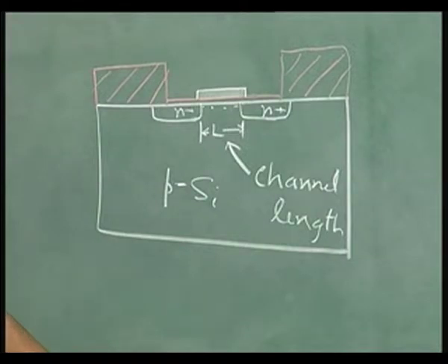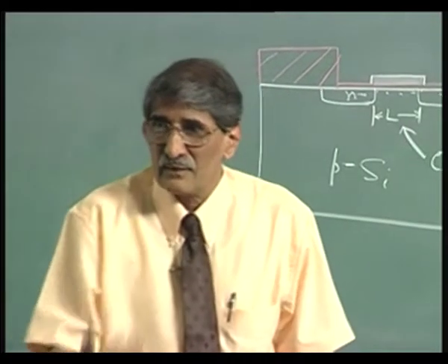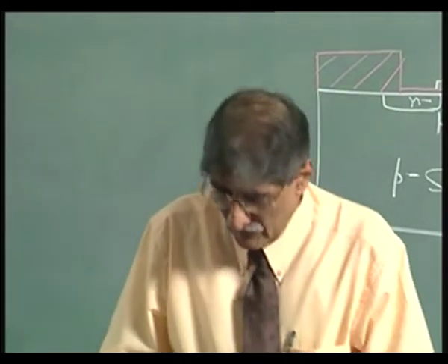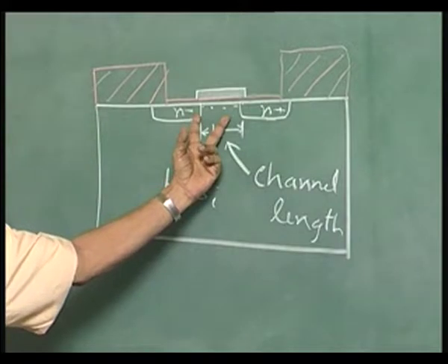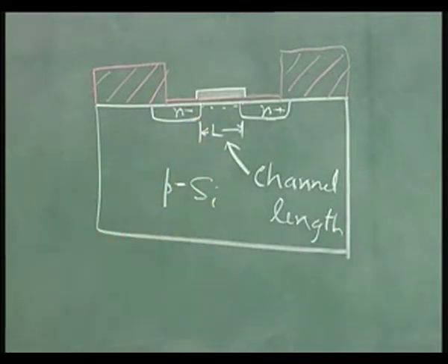You can go down to 0.1 micron, that is the technology today. But getting down to 0.1 micron is very difficult. In India, we do not have 0.1 micron technology today. What we have is, we can define channel lengths in the semiconductor complex, I think about 0.8 microns.